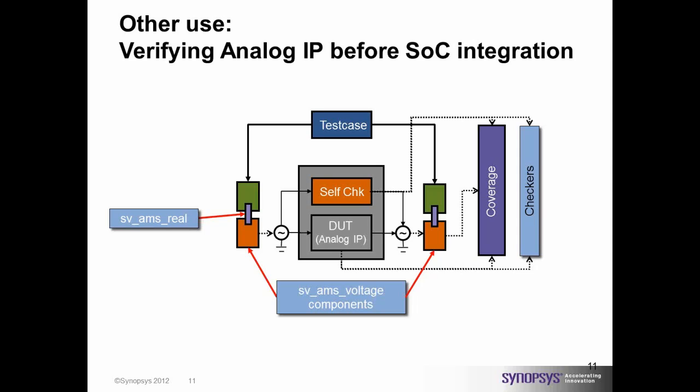But I want to see a test where I constrain the V in from 0 volts to 1 volt, and then observe the output, convert it to integers, and see if there is a self-check, where the exact value of the ADC output matches the value which V in is supposed to bring in. So that's a very simple example I have taken to demonstrate the purpose.